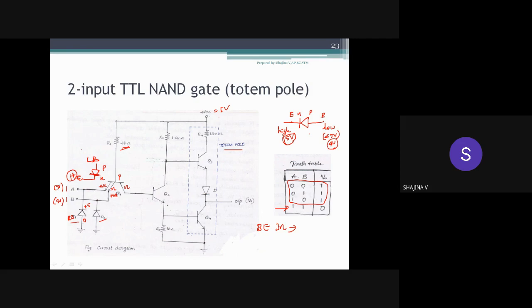When you say forward bias, it is reverse, right? Because when we say forward bias, you should always think of high value to positive terminal, low value to negative terminal. If both are positive values, then if the highest value is at the positive and the lowest value at the negative terminal, we can say that it is forward biased. Or in the opposite case, it is reverse biasing. So here, high value is applied to the negative terminal and low value to positive terminal, which means this base emitter junction will be in reverse biased condition.